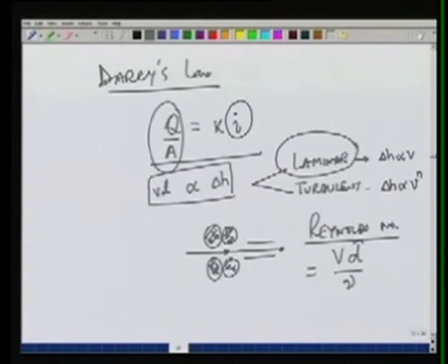This diameter in pipe flow is the diameter of the pipe. So here, since the diameter of the pore will depend on the diameter of the grains, we can put the grain diameter here, which may be let's say D10 or D50 or D90 of the soil. Velocity V we can put as the Darcy velocity, and this nu is the kinematic viscosity of water.